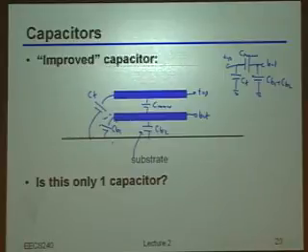Yes? If you lift the bottom plate, then you'll decrease the capacitance between the bottom plate and substrate while at the same time increasing the relative capacitance of the metal plates. Okay. So you said a few things in there, all of which were correct. But we're going to come back to, I'll ask you maybe some more questions as to what you actually can do and what you can't do.